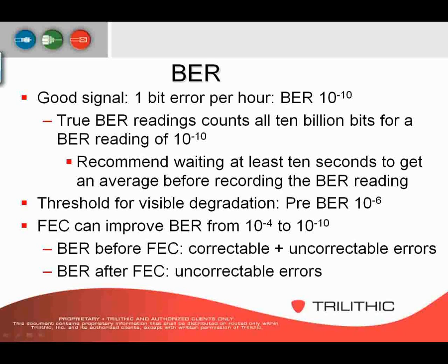Now, when you're looking at it as a true BER measurement, it takes approximately 23 to 25 seconds to look at a billion bits. So you need to look at it for at least that long so that you can base your readings off of a billion bits.